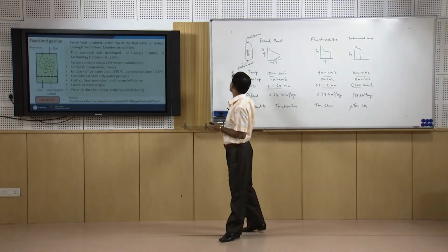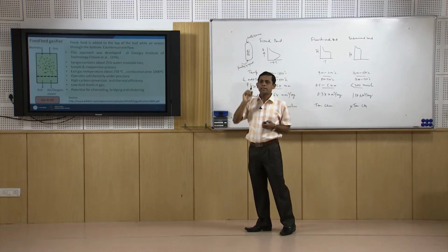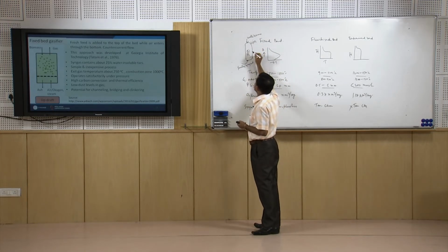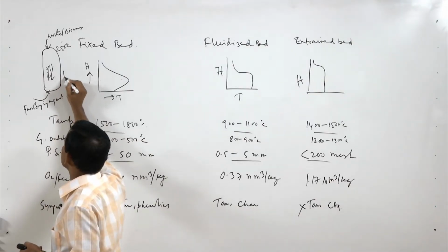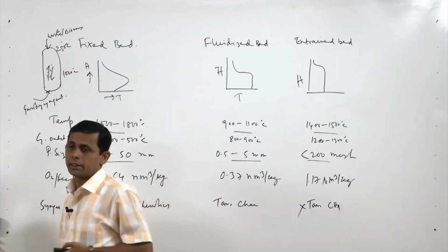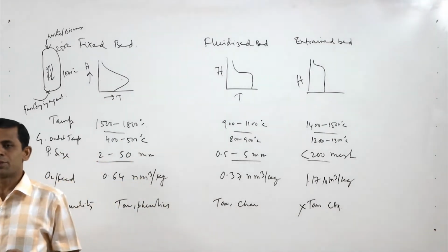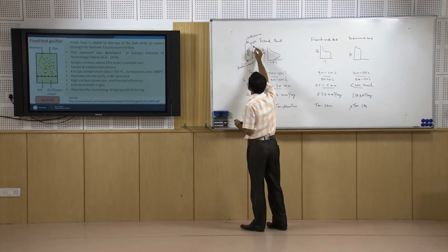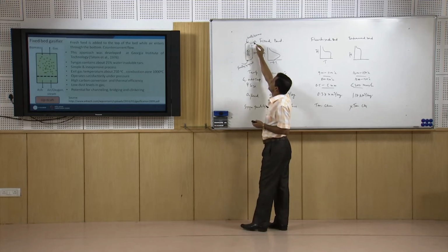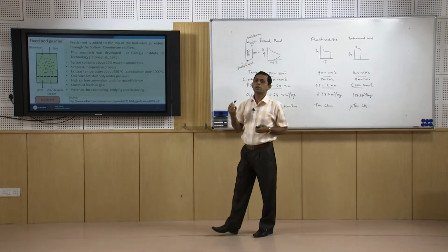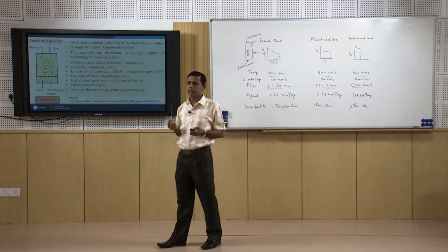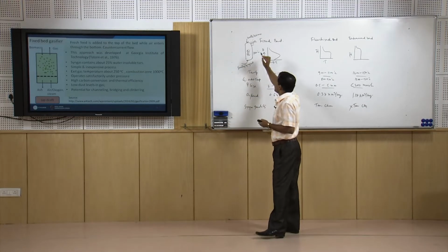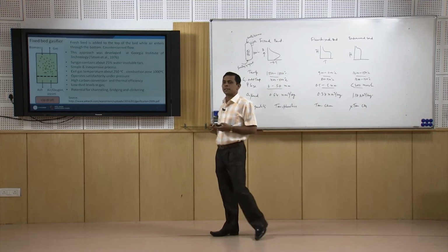So, these are the disadvantages of this process, and another most important disadvantage is that the outlet temperature is 250 degree centigrade, whereas the inlet temperature inside the combustion zone is around 1000 degree centigrade. This is for the updraft fixed bed gasifier for biomass and waste. So, due to this low temperature and less contact time, the syngas will contain a high amount of tar, around 25% tar is present in case of updraft biomass gasifiers, and to remove this disadvantage of the updraft gasifier,